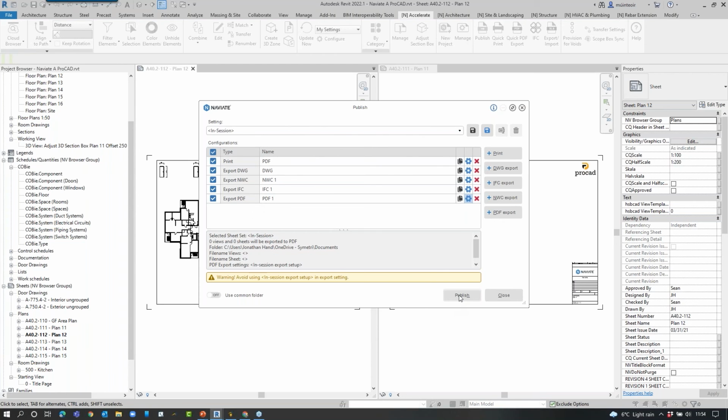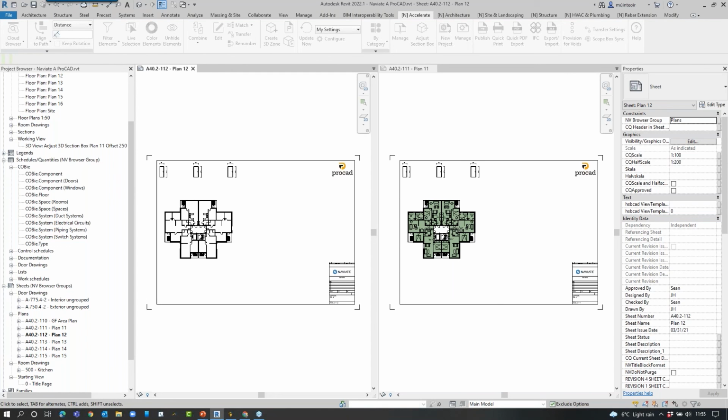And then you just come in and you can click publish and it will go through. You can override everything and put them into a project folder, so it will take all the folder locations and drive that behavior into a single place. It does work with putting stuff into BIM 360 as well through the desktop connector. And then you simply click publish and off it goes and publishes it, and you can just build them routines. So instead of going in on the Fridays as we do and spend an hour doing it, we can just automate that in a single click.